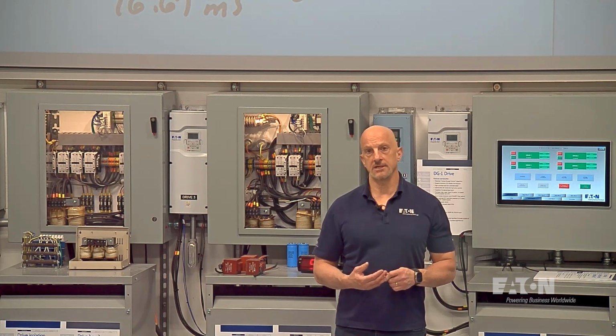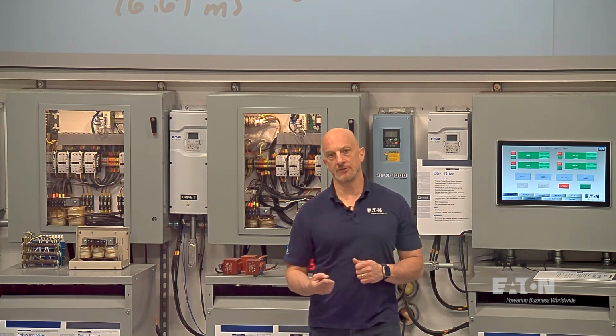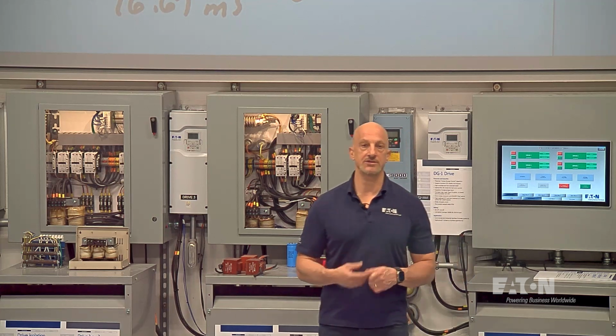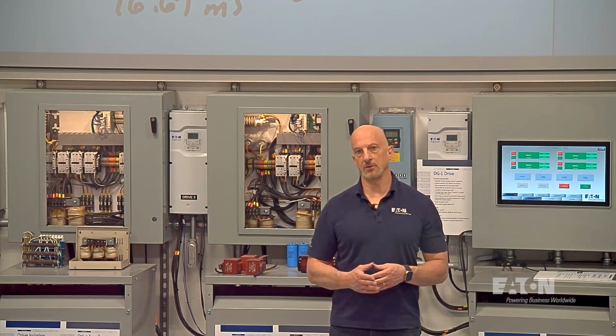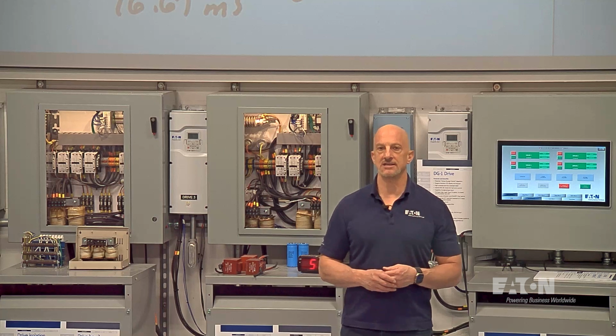So, is voltage distortion a problem? Yes, it can be. But what does it cause? It causes misoperation. Why does it cause misoperation? Mostly from the notching of the voltage waveform that causes either multiple zero crossings or distortion around that 0 point that makes it look like it's not 60 hertz.